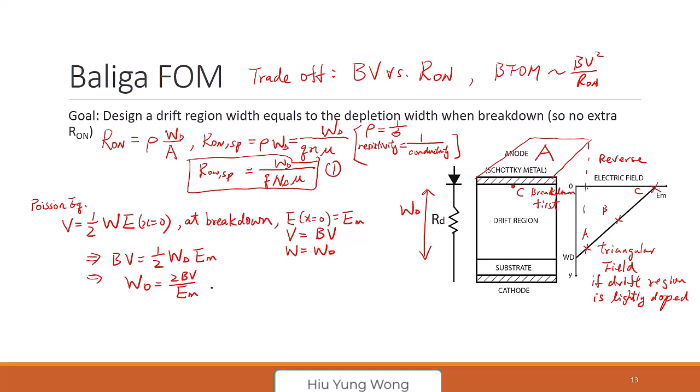Okay, but do you remember what WD is? This is a depletion width, right? So we just use the depletion equation, 2 epsilon times the BV divided by Q Nd. Do you remember? I'm going to erase it, but at that time we said the depletion width of a transistor is 2 epsilon 2 phi s if it is in inversion, divided by Q Nd, something like that. Here, the potential across is the BV, not 2 phi s. That's why this equation is the same if you try to do an integration.